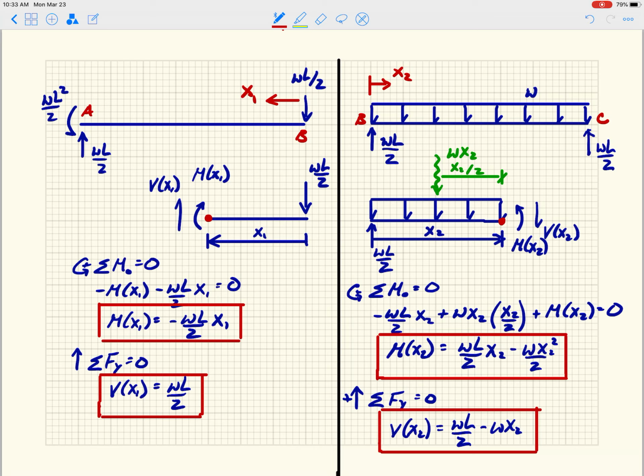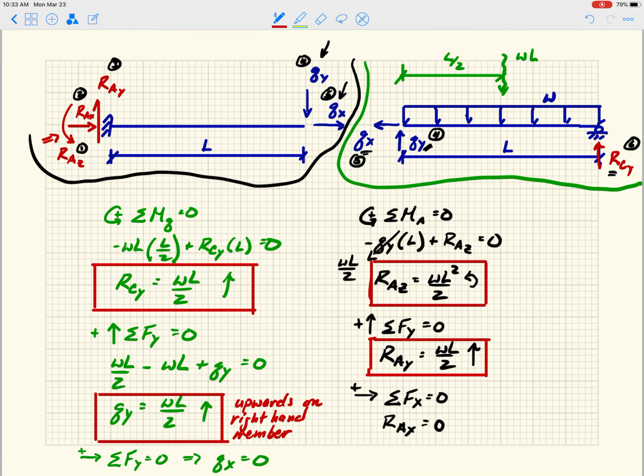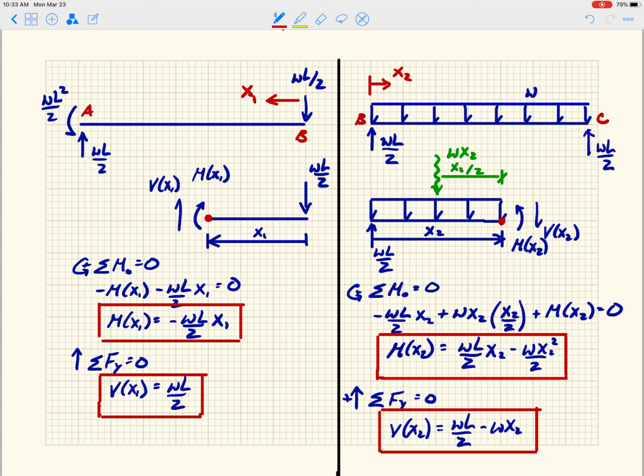The release rule is you break it up. When you break it up, you basically turn a single problem into two problems, right? How are they linked? They're linked because these guys are equal and opposite forces. That's how they're linked. So we choose one, we solve for those internal forces, the actions at the release. We then flip them over and apply them to the other side of the structure. That's why it's not two completely separate problems.